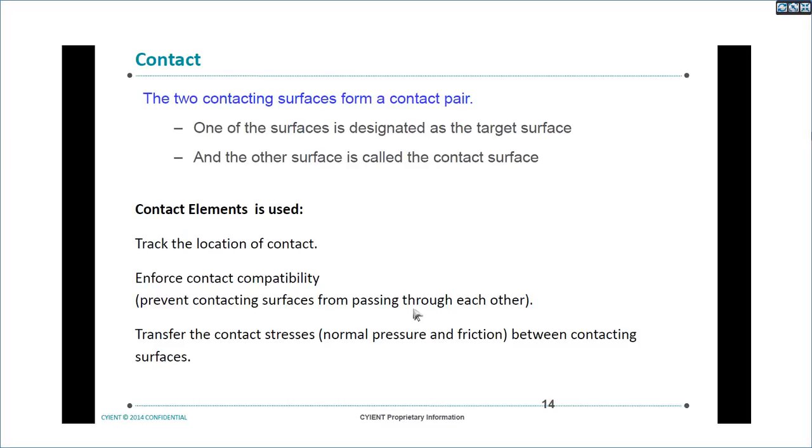So it is very important for us to simulate a contact here, so that this target or contact will predict this contact and transfer contact stresses between the contact surfaces. Of course, it will transfer the loading between the two assemblies.